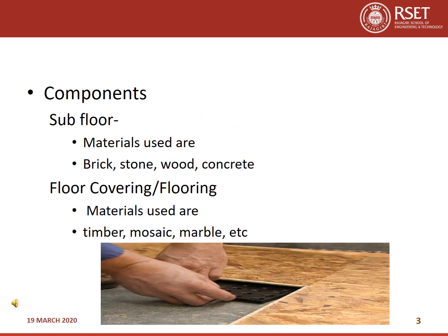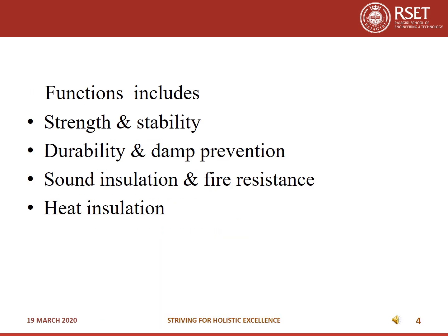Components of a floor include subfloor. You can see in the figure. Subfloor can be made by using brick, stone, wood, concrete. Floor covering above the subfloor can be made using timber, mosaic, marble, etc. Functions of the floor include strength and stability, that is, it should be able to withstand the load coming on it, durability and damp prevention, that is moisture prevention, sound insulation, fire resistance and heat insulation.